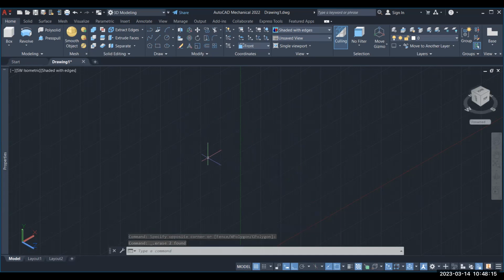Okay, so this is simple command called what? Revolve. Now sweep. Here another thing. So when you are going to use sweep command, like generally, if you want to generate a solid along a certain path, define some path. So throughout the length of that path, you want to generate some rod, like circular rod. Then you can use sweep option. So how exactly, you just see now.